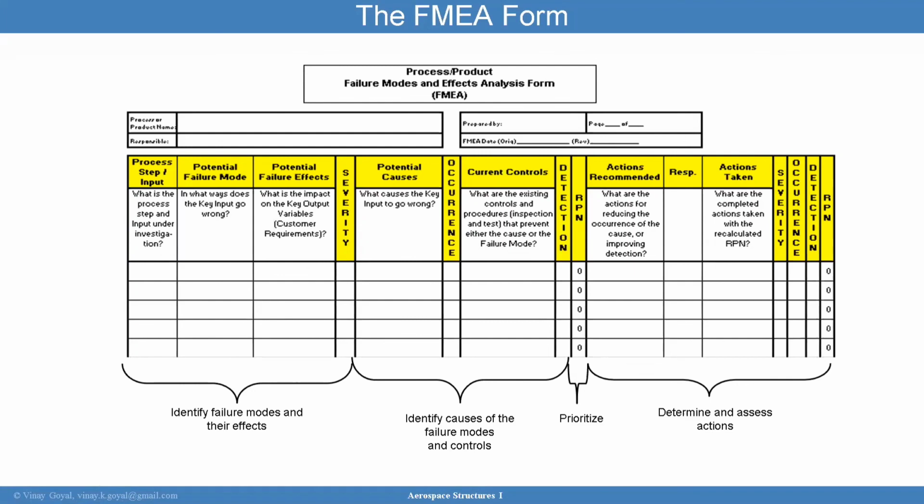Yeah, I think this very well illustrates the different parameters that we were referring to: severity, occurrence, detection, and the RPN, which is the product of the three of them. At least in my experience with FMEAs, whenever you have a high severity and/or a high RPN, your own industry will dictate what the threshold is. It's very important to always associate a recommendation and fill out what actions were taken. As a result, you will repopulate your parameters to see how effective that action really is. There you go. I totally agree.